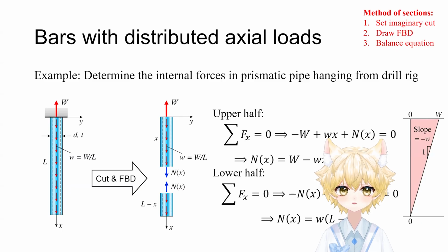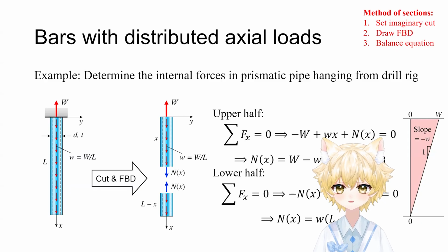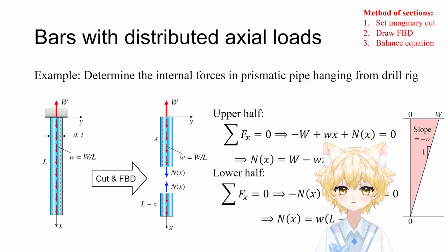Remember, when we calculate the overall weight, we use the whole length, right? The whole length is L. And we need to solve for the reaction force of the whole structure, because no matter where we cut, our N of x is just a balance with the weight of our lower part, right?